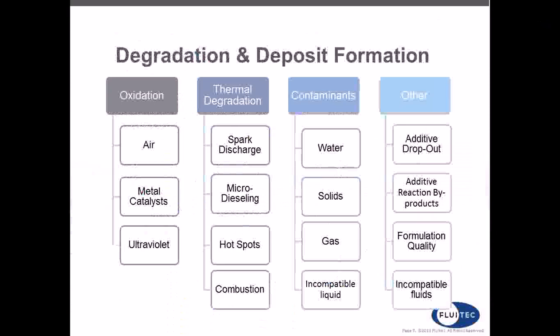Another thing that can speed up, promote or contribute to deposits are contaminants. So certainly water contaminants, additional solid contaminants. Gas is a contaminant as well. We see a lot of this in compressor applications where some of the processed gases can get into the lubricant and cause some unique reactions and help accelerate the formation of deposits. And incompatible liquids as well. Not only incompatible cleaners and detergents, but also incompatible lubricants could inadvertently be mixed into the fluid.